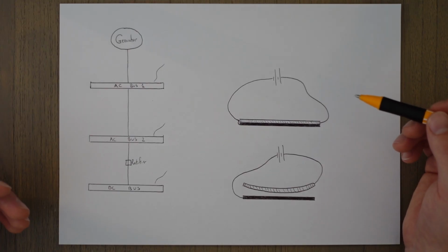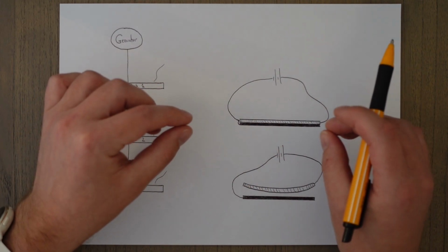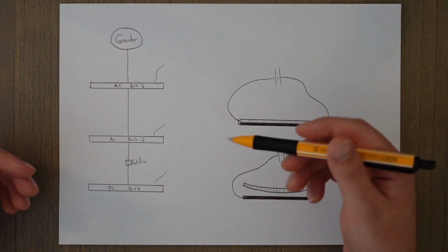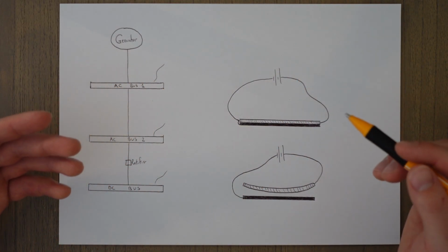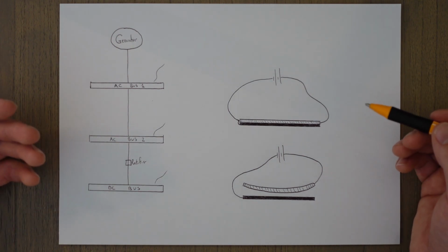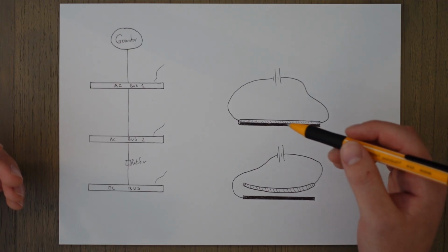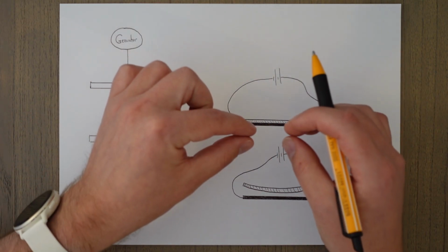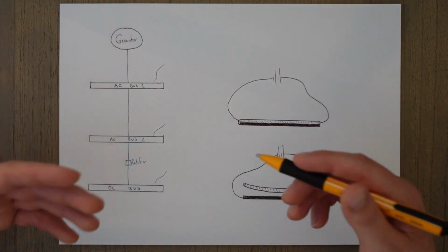This is essentially a reusable fuse. A fuse is just a thin piece of wire that is designed to overheat and melt when a certain value of current goes through it, therefore breaking the circuit and protecting components from getting damaged. With a circuit breaker though, we use two different metallic strips and they're connected within the device itself, and when they are connected, it allows electricity to flow.